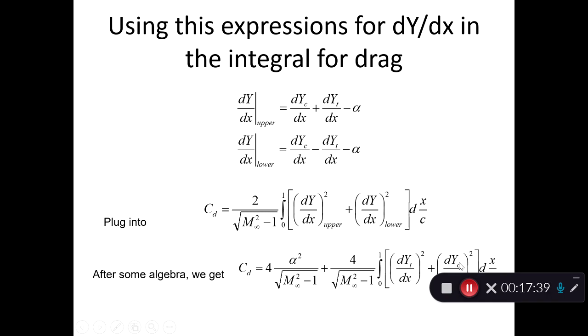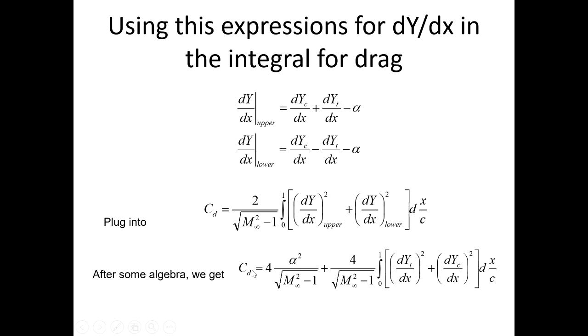That's why supersonic aircraft such as F-15, F-22, F-35, Concorde, they tend to have as little thickness as possible, as little camber as possible. That means you don't store the fuel inside the wing, you store the fuel inside the fuselage. You don't store the landing gear or anything inside the wing. You don't put anything like a supporting system for actuators, for flaps, slats, because anything that increases the thickness is going to quadruple your drag, so you want to avoid it.